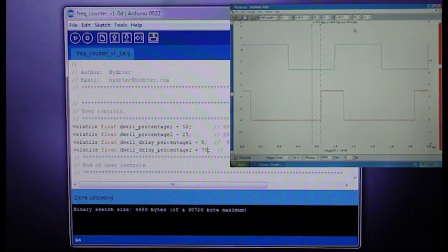So there's the two measured sets of latencies for the two different settings for the two sets of tests we've just run. So far, so good. Once more, with the current dwell percentage set at 25%, you see it's not sensitive to the actual duty cycle settings of the input pulses, because, as I said earlier, we're measuring leading edge to leading edge.